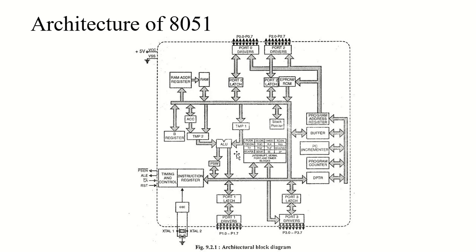Now for selecting the register bank, 2 bits RS0 and RS1 are provided in the program status word, and if any of the register banks are not selected, then the program can use the area from 00H to 1FH as simple scratch pad RAM or general purpose RAM as well, right?